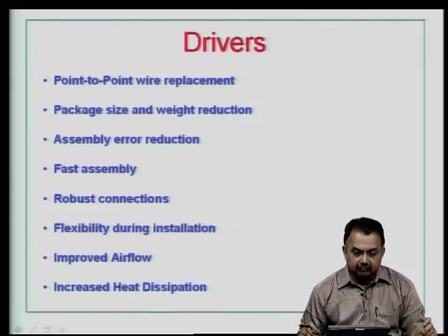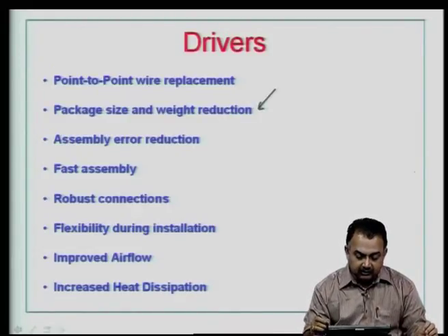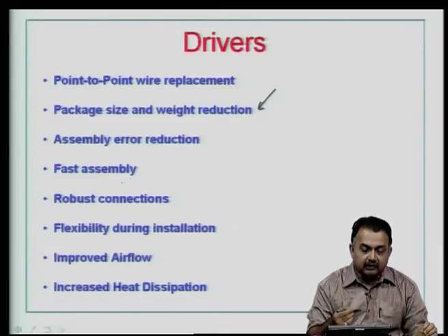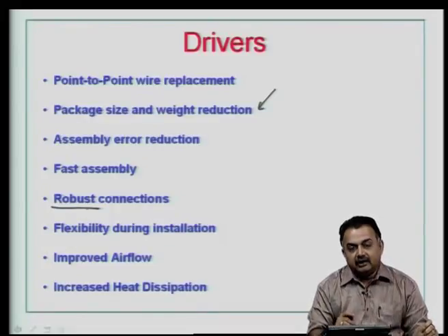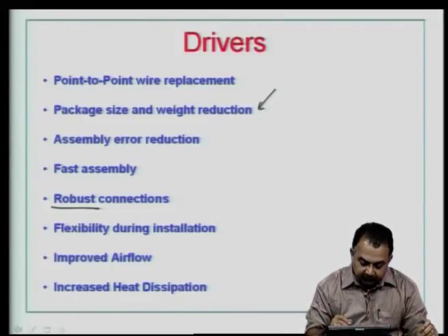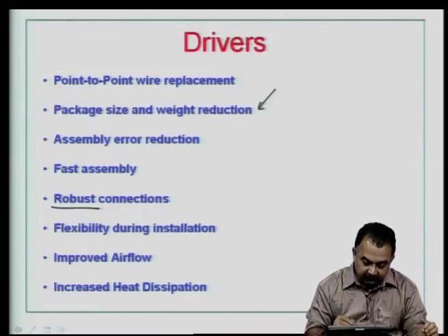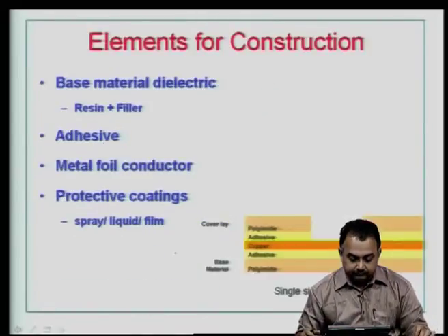The drivers for flex circuits are point to point wire replacement, package size and weight reduction, again a very important point, assembly error reduction, and fast assembly, because you do not have to deal with bulky wires, you deal with strips. They are in fact very robust; although they are flexible, thin and lightweight, the connections are robust. Flexibility during installation, improved airflow and heat dissipation in devices compared to rigid boards.